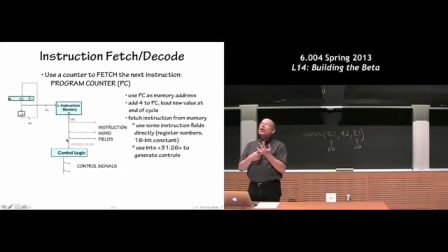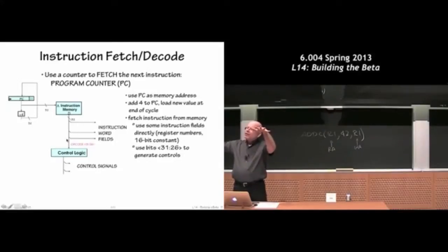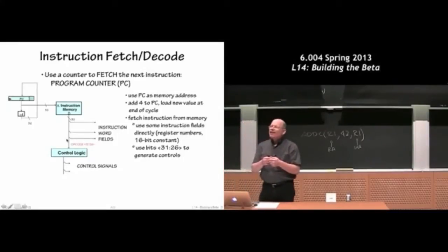Oh, you mean you're thinking about the control signals that go into the ALU, which were 5 bits of control signal. Those will be information that we're going to have to generate from the 6-bit opcode. The opcode in the instruction is not the same thing as the ALU control signals. And we'll discover that the 5 ALU control signals are only some of the control signals that we'll need to generate from the 6-bit opcode. You might say, couldn't we pick a clever encoding so that the 5-bit ALU field was somehow embedded?